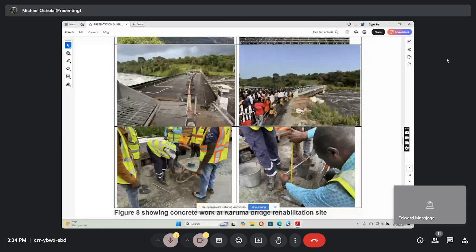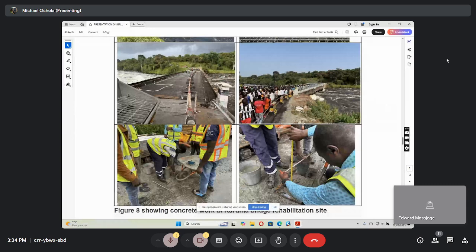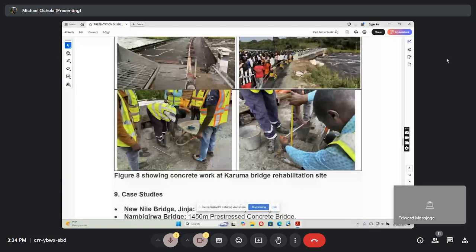Now, quality controls at the time of casting concrete. You have read about this. We shall not waste much time here. This guy is doing a slump test, a workability test, and their requirement, if it is a collapse, shear, or true slump, there are 3 types. You can look at it, then you measure. Normally it is specified. For concrete using a pump, it has a certain amount of slump to measure. If it is going to be heavily congested, you need flowing concrete. It also gives you the amount of slump you should measure. So basically, that is exactly what happens.